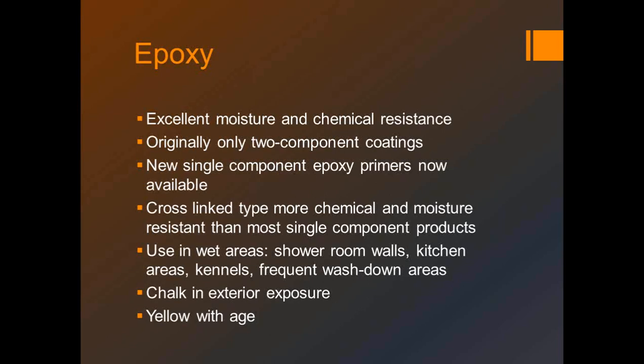Well, there are some cementitious acrylic blends that you can use to purge the surface of the wall and pretty much take the joint lines out of the wall, and then come back with a couple coats of epoxy on that and have a very attractive wall and get a very durable surface over a CMU wall.